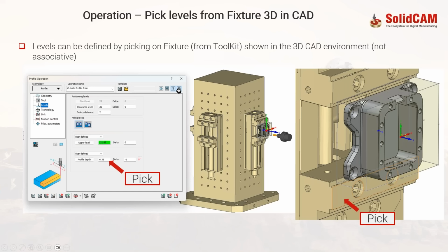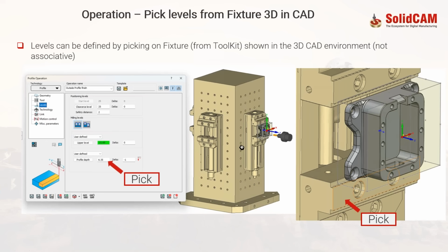And this fixture is not only for preview, but you can actually use it in any of the levels and grab any data that you want for the levels. How cool is that. One detail here: because this is STL, it is not associative. So pay attention that you will click on these geometries, but this field over here will not become green. It will not be associative. I mean, it's reasonable, of course.